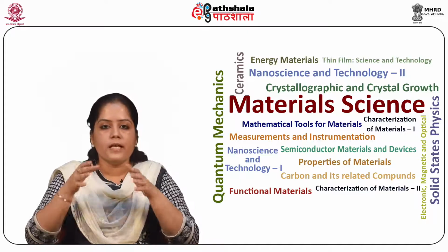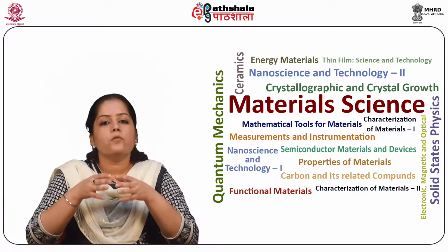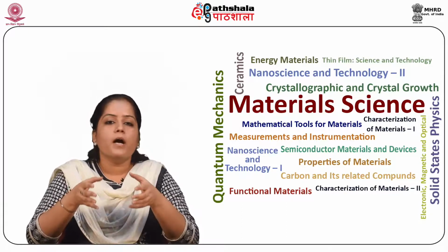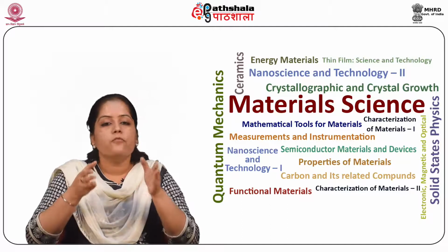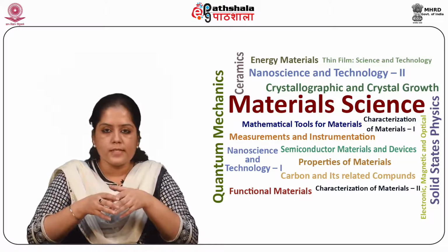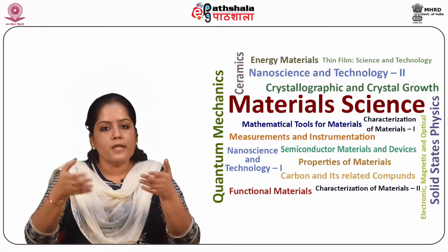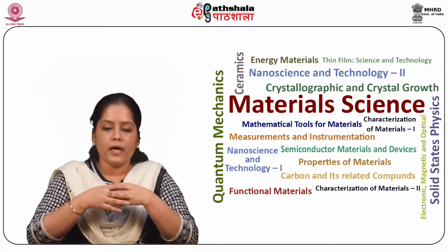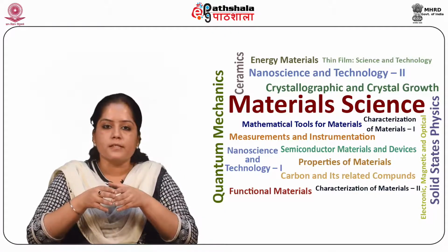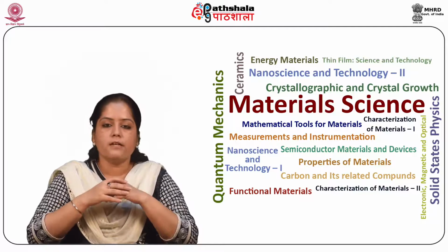Toughness depends on the energy consumed during crack propagation. So any microstructural feature which impedes the crack propagation, requiring more energy consumption for crack propagation, or any process which introduces stresses which oppose the applied stress, would lead to an increase in the toughness. On this basis, the mechanisms for toughness increase can be categorized broadly into the following categories.